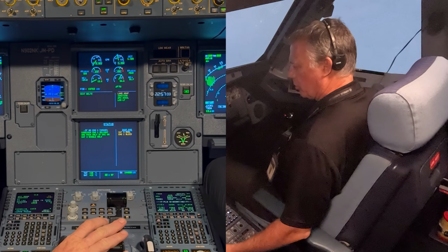Remember to keep your hand on the engine master switch in case of a start fault, which would have to be manually aborted since we're airborne. We'll skip to the point where the engine relight is complete.